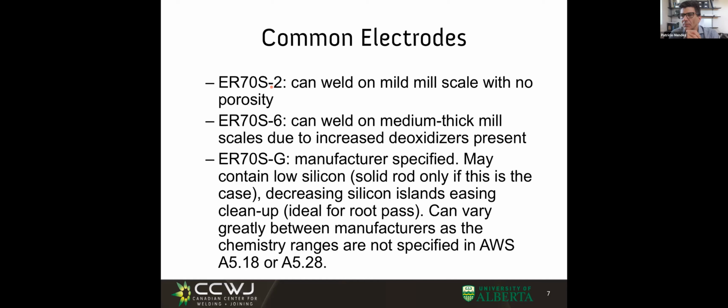And I have a question about silicon inclusions. They can happen, but in MIG, typically what happens is they float to the surface. After you weld with MIG, you see sometimes kind of yellowish, glassy spots over the surface of the weld. That is the silicon oxide. That's essentially glass. Those are silicates that come from the silicon that reacted with the oxygen and floated to the top. So now what you would say, okay, I got a stronger wire, I'm happy.